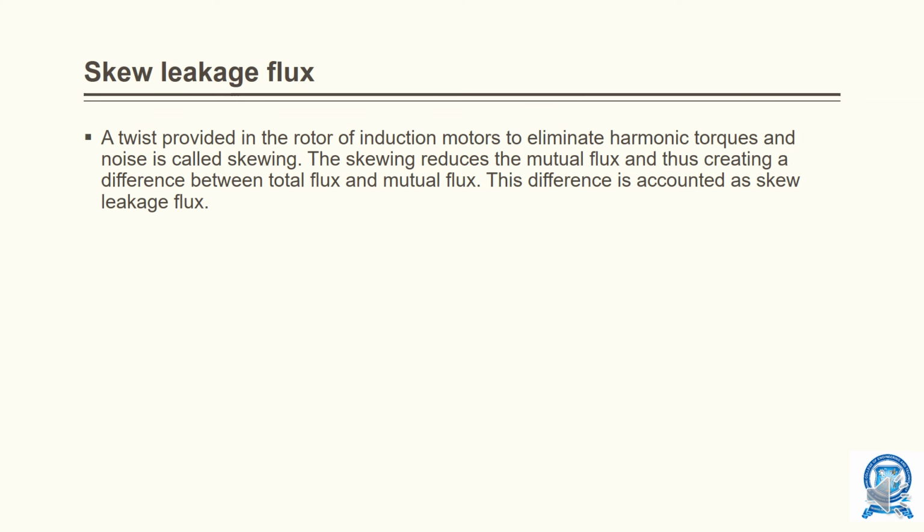Skew leakage flux. A twist provided in the rotor of an induction motor to eliminate harmonic torque and noise is called skewing. The skew reduces the mutual flux and thus creates a difference between the total flux and mutual flux. This difference is accounted as skew leakage flux.